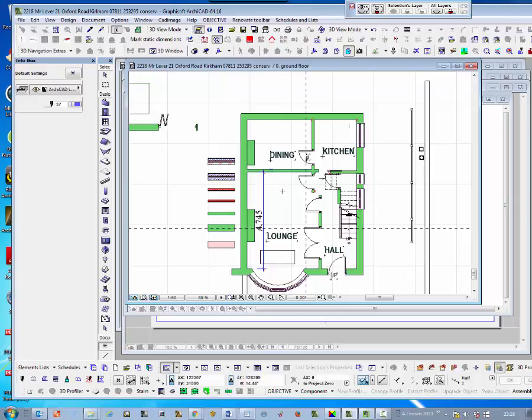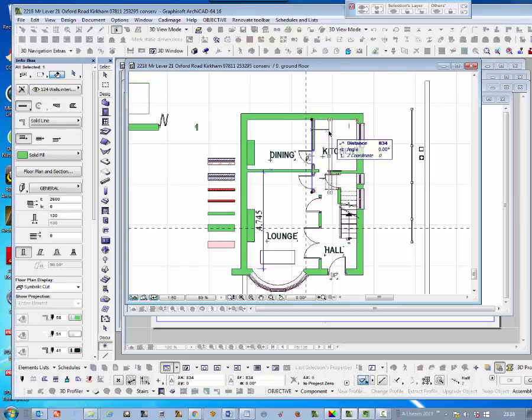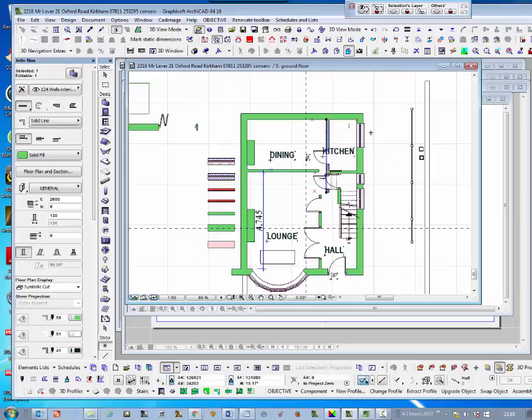So from that side, pressing X this time because we're going across the drawing, 3840 plus, because it's going across in that direction, and again shift click on that, Control D, and drag it over by that side of the wall.